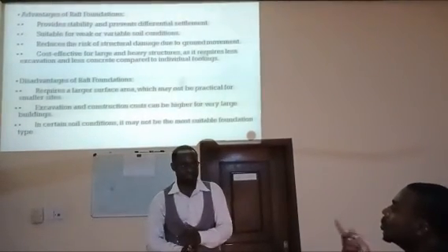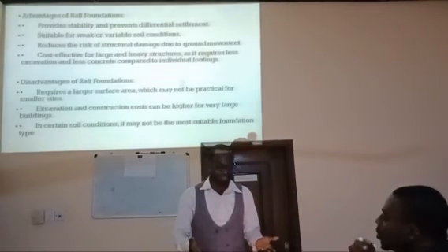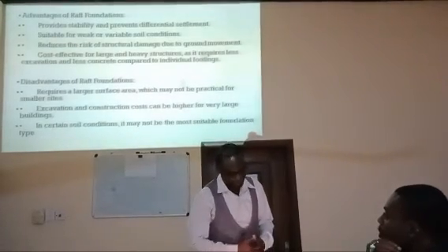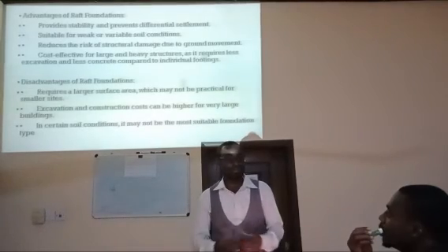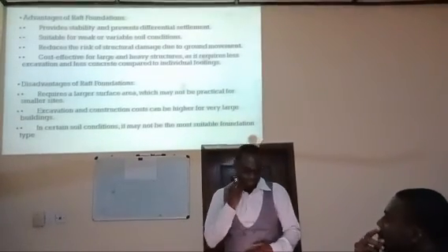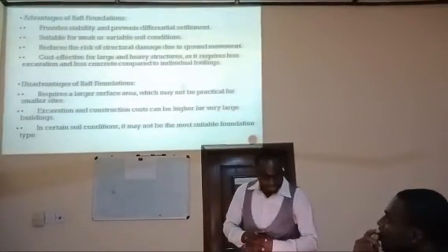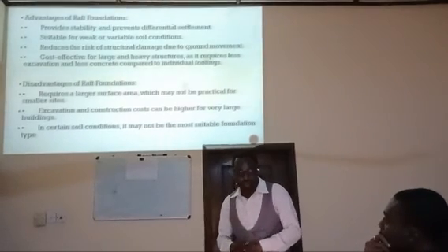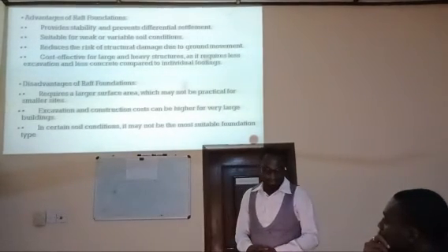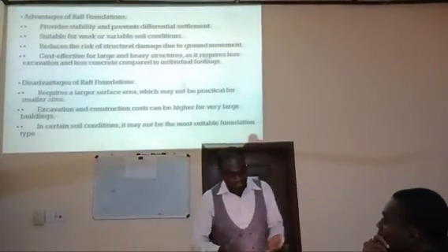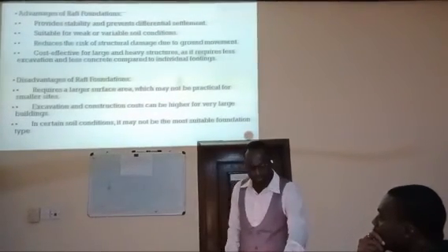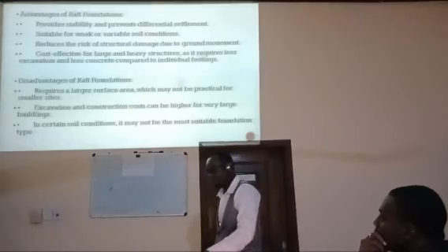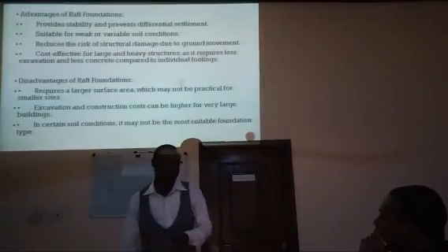Because some buildings, when you evaluate them, you should be able to check between deep foundation and shallow raft foundation which one should be used. I told you stability. Can raft foundation carry it? Yes. Now, if raft foundation can carry it, what is the cost of raft foundation and what is the cost of deep foundation? So when you now compare, you see that raft foundation will be quite cheaper, so you can manage raft foundation there properly. Stability, economy, guarantee. So that's what he's looking at here.